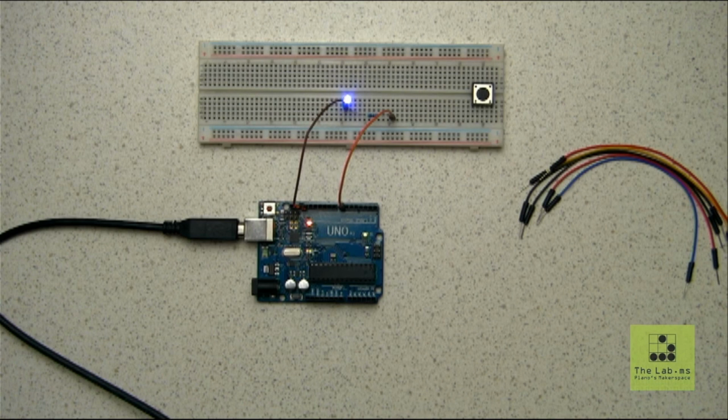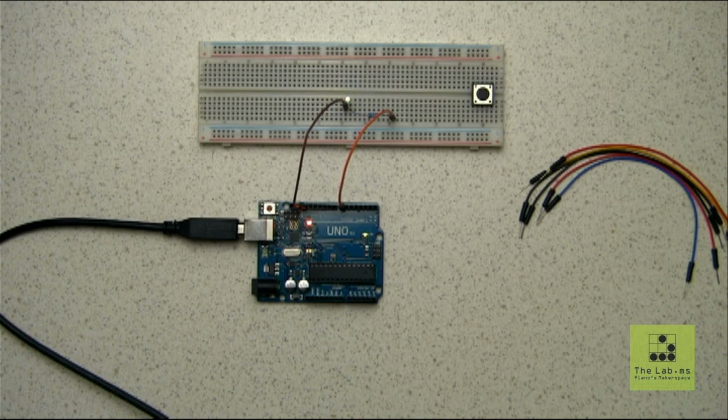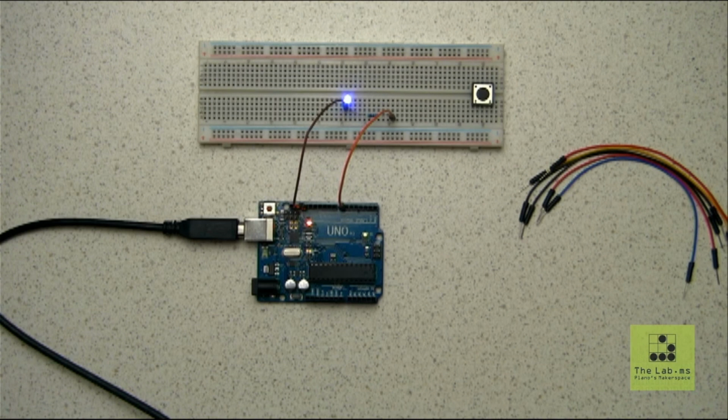Let's see. How does it work to connect to, say, just a regular light bulb? Yeah. So if you wanted to control a light bulb, like on and off, you need to power that light bulb externally, because it'd be 120 volts AC. So that would need to be powered externally, but then you could use what is called a relay, and that relay would control basically a switch to tell that circuit to go on or off. And then the control for that relay would be controlled through the Arduino.